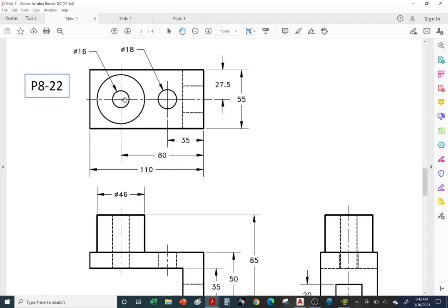We'll add the diameters for the holes. Notice we only add diameters for circular holes, but not circular shafts. Since this circle represents a shaft, we need to place the dimension down at the front view, the rectangular view. Go back to your lecture notes in case you forgot about rectangular views versus circular views. All right, so let's go ahead and do some dimensioning.